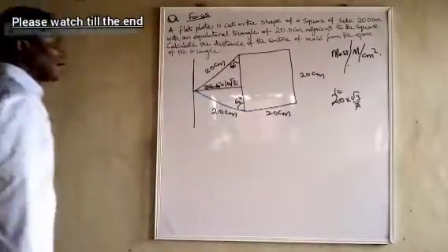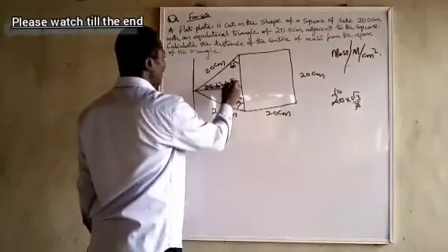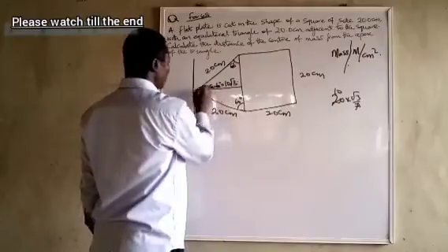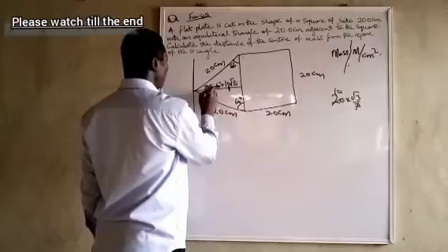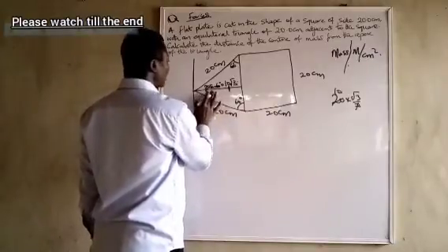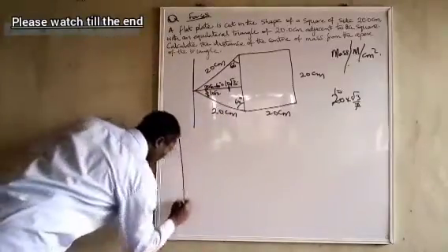We also know that the center of mass of a triangle is 2/3 of the way down from the apex, so from the apex to the CG is 2 over 3 times 10 root 3. So I'm going to make a table like this.